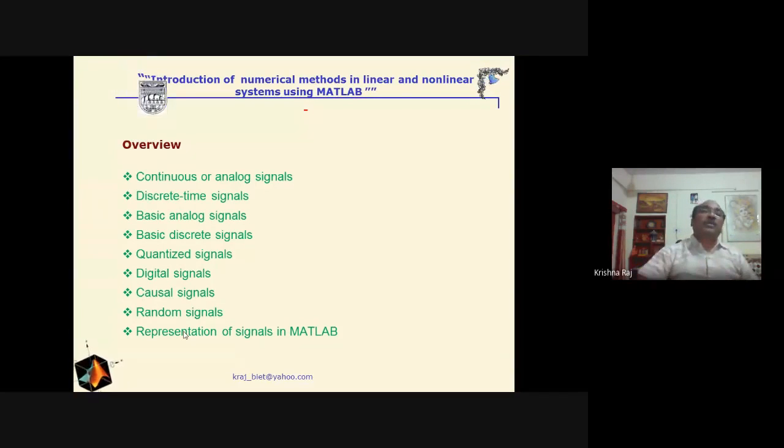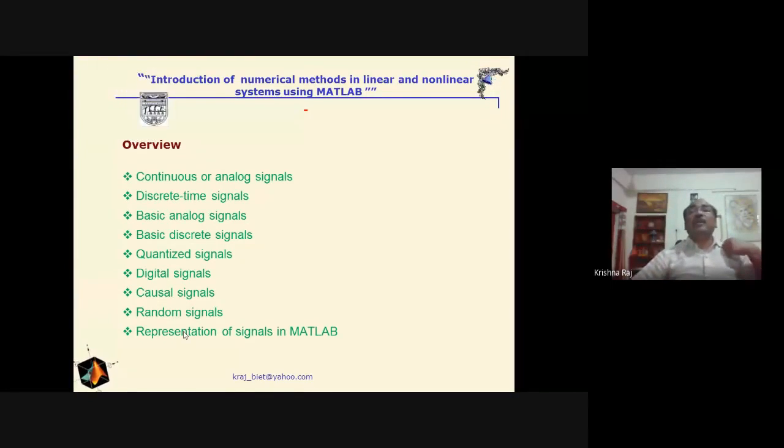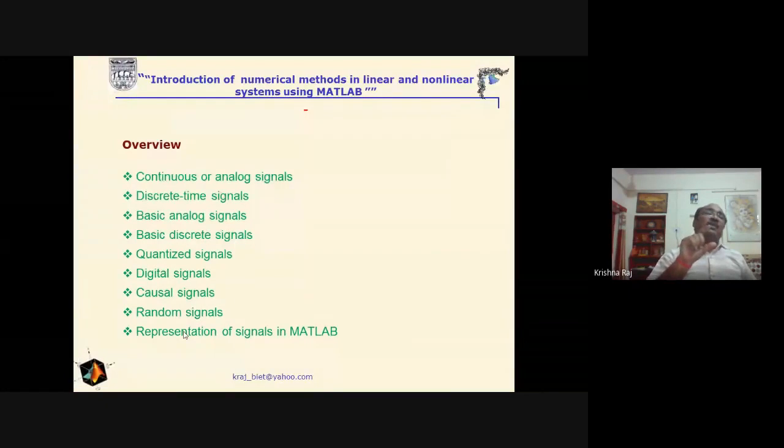It has a fast change from 0 to some value, and again back to 0. If we see the pulse here, the value changes from 0 to some value, say 1, then remains 1 for a particular duration, then again becomes 0. So we will find two ranges of frequency. In zero time the test signal value changes from 0 to a particular value, that is infinite frequency: the inverse of zero time becomes infinite frequency.